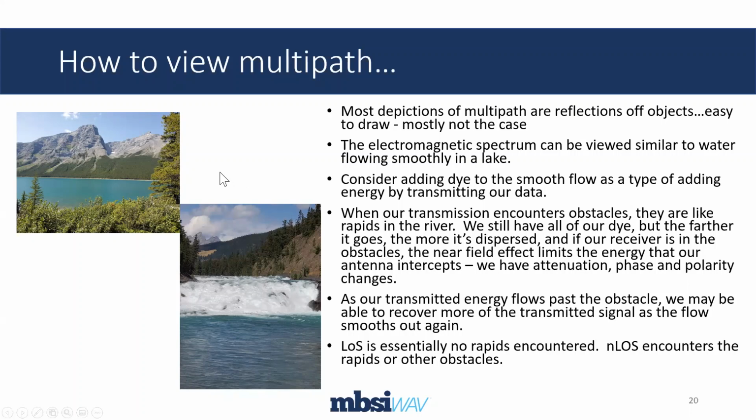So it's important to know this characteristic, that when we have a CPE that's located, let's say, right in the middle of a forest, our attenuation from that forest is going to be much more than if we have the CPE installed at the very same height, maybe even, once we get past the trees. So if we're, say, a kilometer past the trees, our signal level might actually be higher than it would be in the trees themselves.